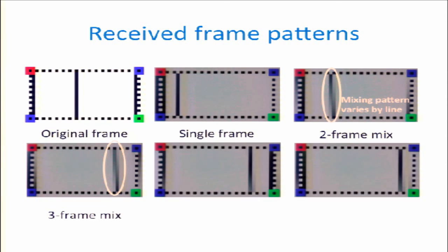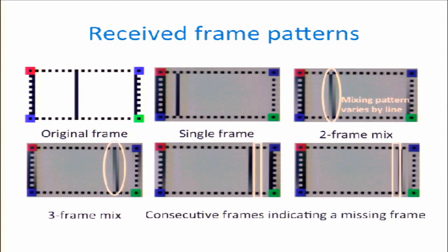And then there's another interesting case. Here, you see two frames. They are actually successive frames that you record. But if you look carefully, remember I said each bar corresponds to a particular frame. That bar is actually missing in both frames. And given that these are successively recorded frames, this means that we somehow skipped a frame on the transmit side. We just lost it for whatever reason.